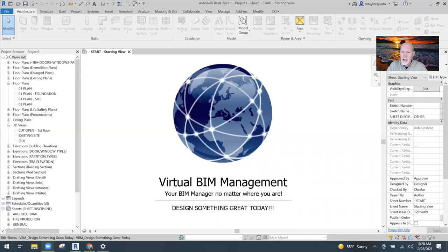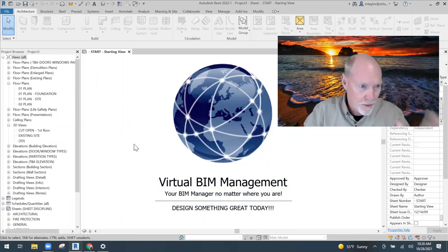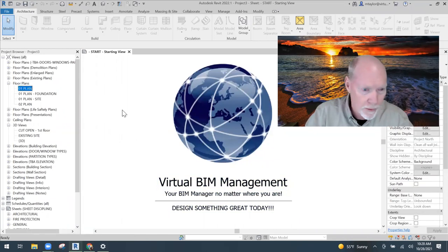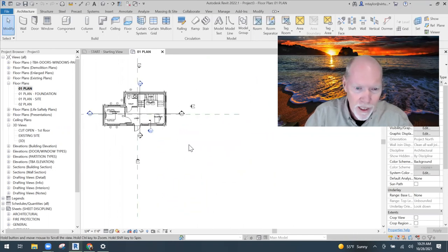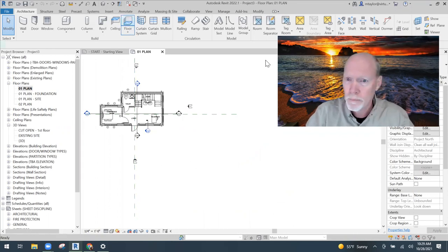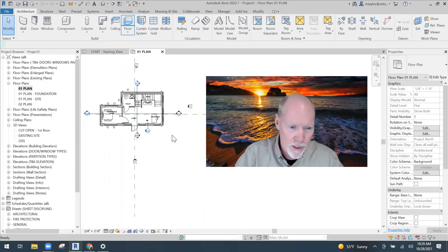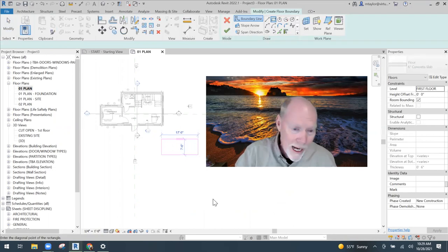All right, so here we are in Revit. Okay, so what we want to do is, let's go to our floor plan. Here we are, our little building over here, but to keep things simple, I'm going to depress the slab. I'm going to put a floor in. I'm just going to put a 6-inch concrete slab, right? Use rectangle, and we're just going to put it out here in front of the building, okay? And done. So we have a slab.